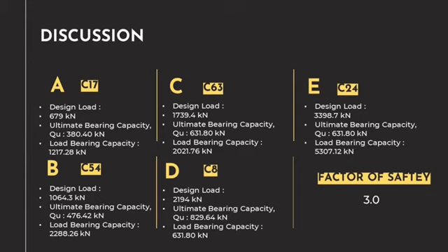I will explain about the discussion. The result that we get is from the bore log of one unit of a 4-story office shop at Jalan Parai Kemang Kesang, Tanjung Gading, Johor. All these columns have different design loads, and the loads were computed using Esteem software. This calculation used the Meyerhof method. Based on the result, all the columns are single piles and have to be redesigned to group piles. This is because all the column NED values are bigger than the QU value. To become a group pile, each NED value must be smaller than the QU value.